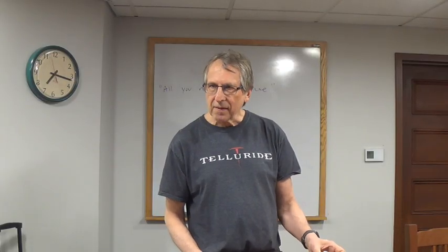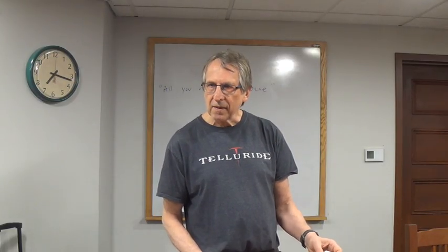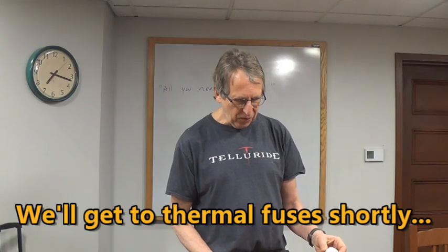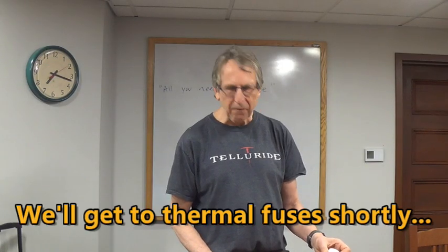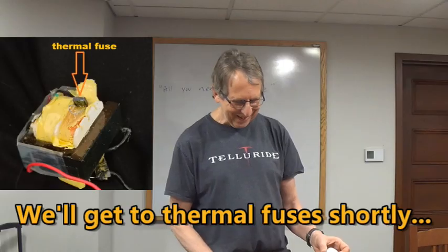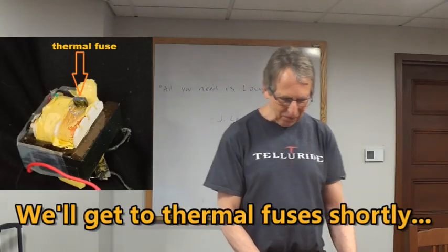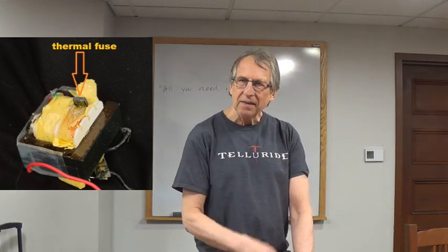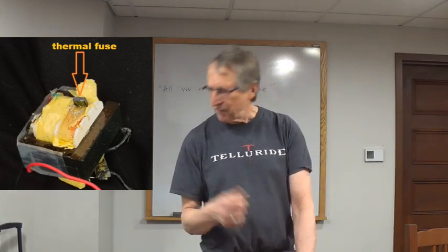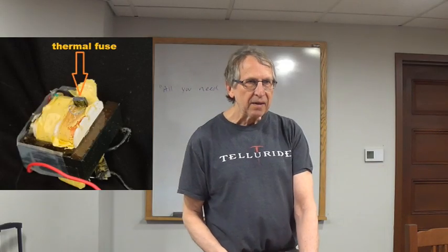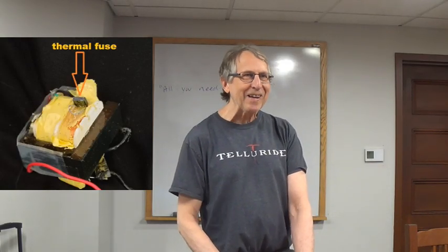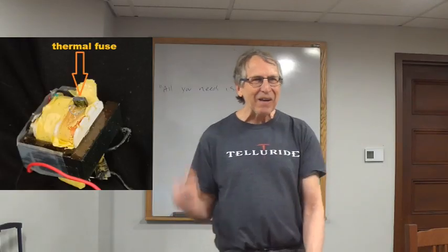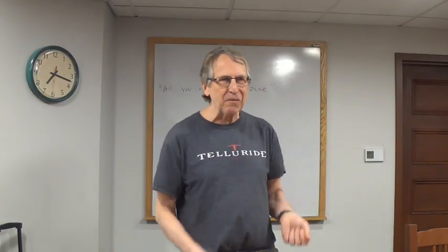So how do you know if something's an induction motor that might actually have that other piece inside it? The thermal fuse. You eventually get to a point where you say, it could be the thermal fuse. And then you take it apart, and the thermal fuse is in the stator, the stationary part on the outside, buried in the windings. Oh, okay. In fact, I have a fan here. How do you replace it? Very, very carefully. Wow. But I managed to revive one fan by changing the thermal fuse.